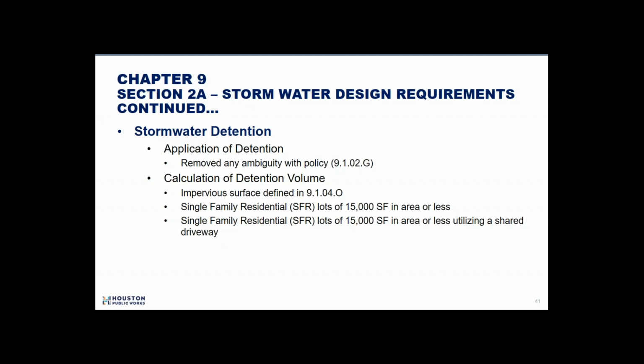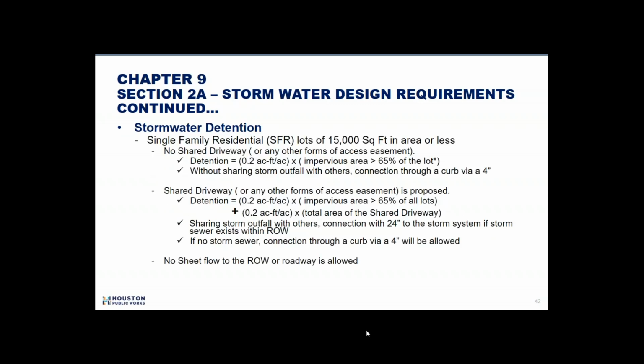So the detention rate is still basically the same for both of them. It's going to be 0.2 for the development, but we're going to change it up a little bit. If you're dealing with a no shared driveway situation, then it's going to be 0.2 over the area, even if you split up a lot into 2 or 3.